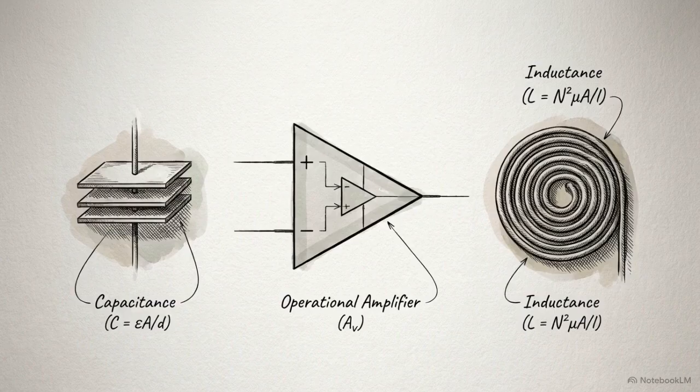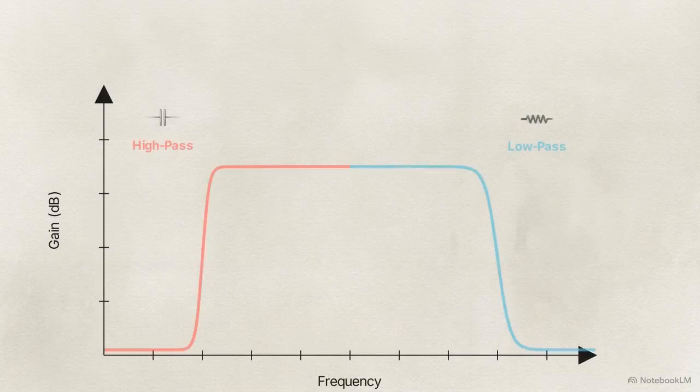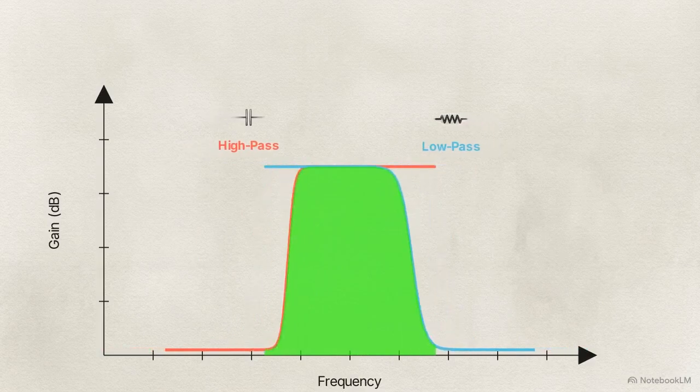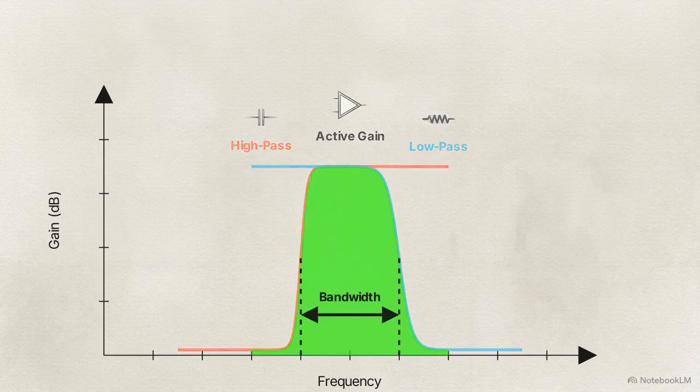Filter design rests on 3 architectural pillars. Passive components dictate the exact frequency boundaries, active op-amps maintain the signal strength, and the filter order dictates the precision of the cut. When we plot a cascaded circuit, we can watch those pillars go to work. The high-pass and low-pass curves slide together. Where they intersect, they carve out an asymmetrical, strictly defined bandwidth in the center of the spectrum.